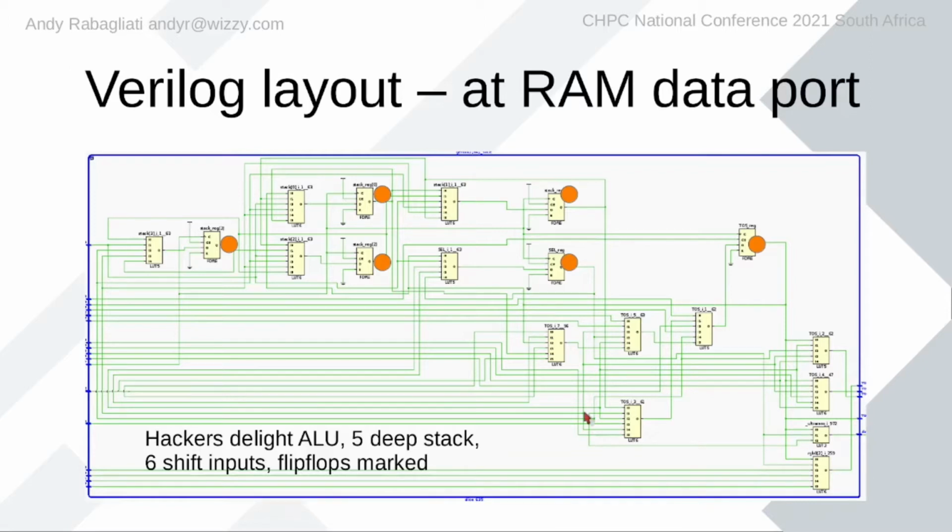This is the Verilog layout. This is the tiny piece of silicon that needs to be put onto each memory chip at the end of each data row. So there is a slice of these in our hypothetical 4 gigabit RAM chip I mentioned earlier. There will be 64,000 of these lined up down the side of the memory array. On my machine I have 1024 in my 1K deep CPU.